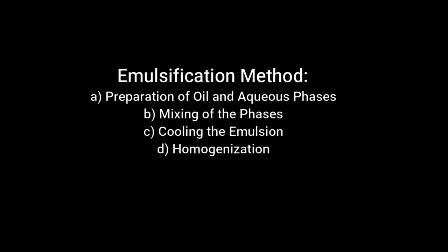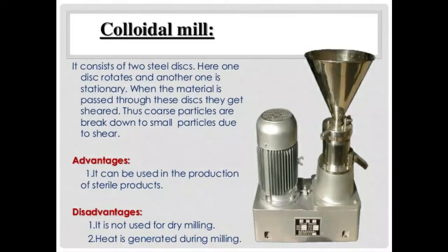Perfume should be added at room temperature in water in oil type emulsions. If the drug is not added in the aqueous phase, then it should be added in solution form or in the form of crystals. Finally, homogenization. The creams or ointments that require further treatment are then transferred to the proper homogenizer, the selection of which is governed by the degree and rate of shear stress required. The choices include a low shear gear pump, roller mill, a colloidal mill, and a valve type homogenizer.